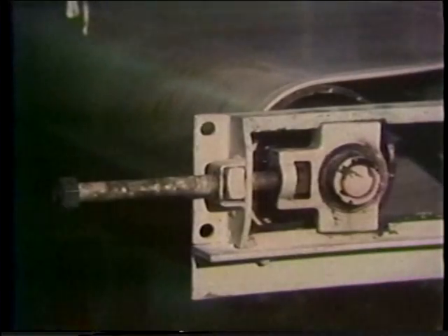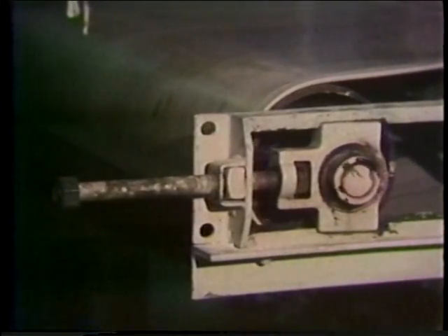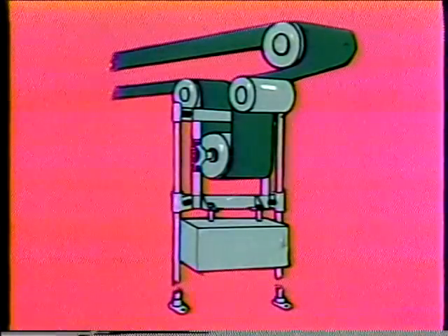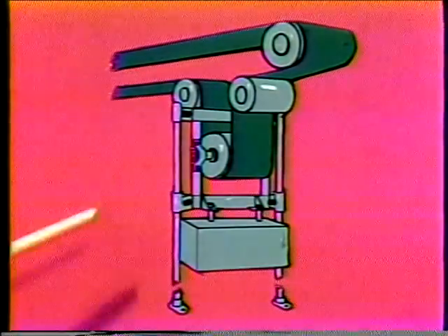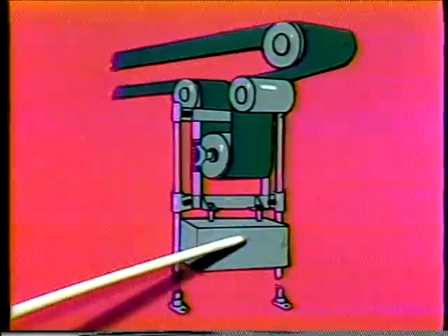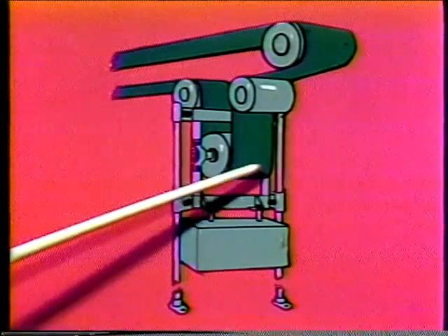In order to keep the belt conveyors tight, there is some sort of take-up necessary because there will be a change in the length of the belt as it's used. It is therefore necessary to have a take-up, and these are either screw take-ups like this or gravity take-ups as shown in this sketch. As you see, this weight hanging on the belt keeps it tight.